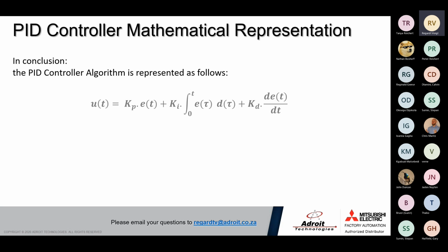From a signal perspective, what the user needs to provide will be 3 signals. 2 inputs, 1 output. So the 2 inputs would be your set point signal and your process variable signal. Many applications only have 1 input signal, which is your process variable, which means the set point will be set via an HMI, meaning a GOT or a SCADA or another method. As for the output, that would be your manipulated value, as we discussed in part 1. That will be connected to your actuator in the field, whether a valve, a VFD, a motor, depending on the application.